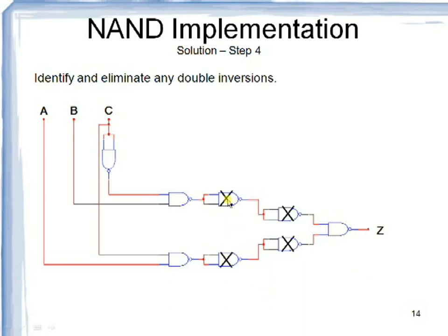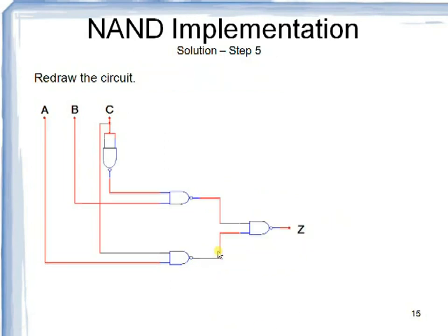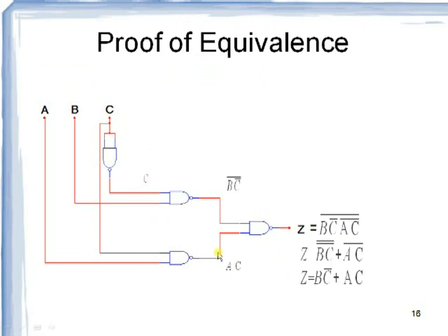Now here this is a NOT gate, whose output is given as an input to one more NOT gate. Therefore whatever output you get here is the same here. Therefore instead of using these two NOT gates, we eliminate them. As we eliminate these two NOT gates, the number of gates required in the circuit is decreased. In the same way these two are again eliminated. Now again we redraw the circuit, and its expression is again similar to the expression that we have seen for AOI logic.